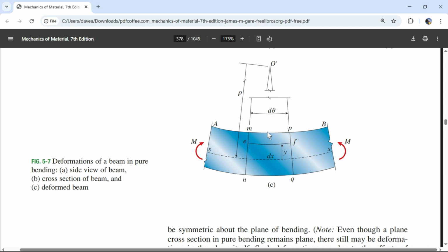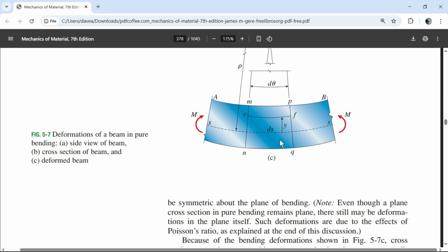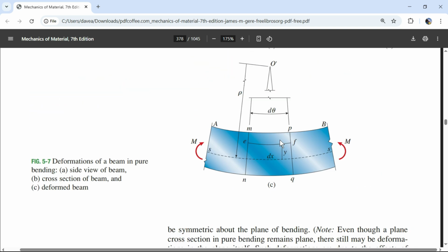So every material has a max compression, a max tension, and a max shear pressure. The general gist of material mechanics is, hey, if you can identify a location, based on geometry and forces, that's going to have a number bigger than that, well, you better design it just a little bit bigger. You know what I mean? Double the size of the darn thing. So yeah, that's just kind of material mechanics in a nutshell.